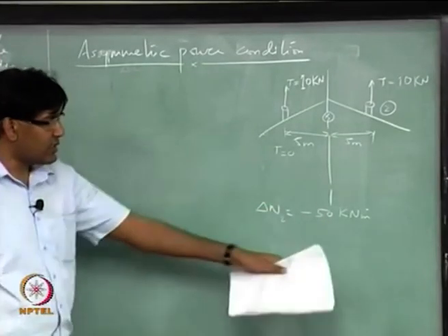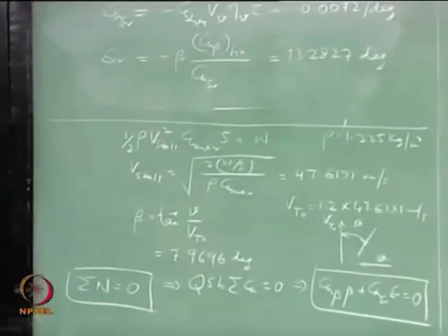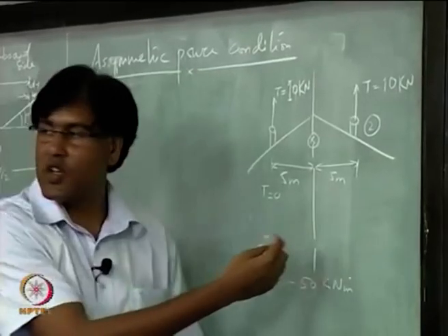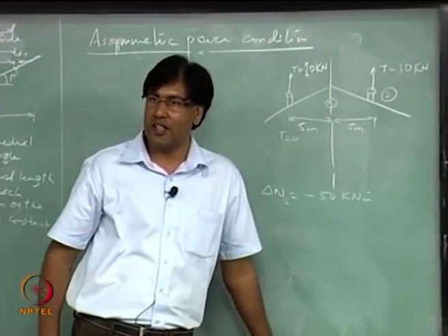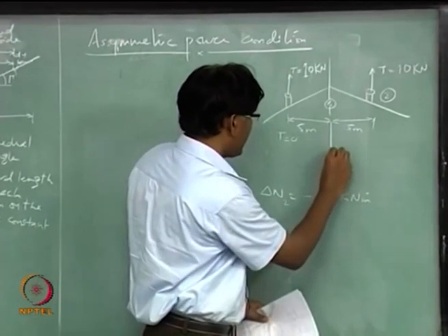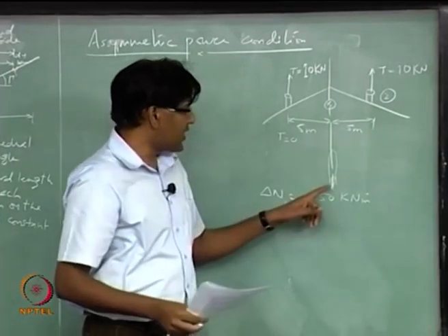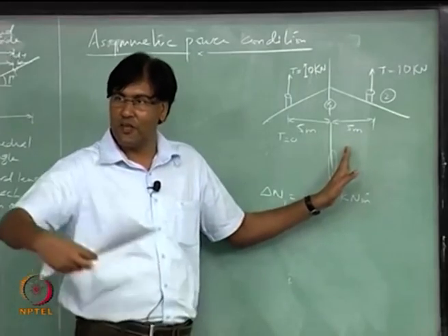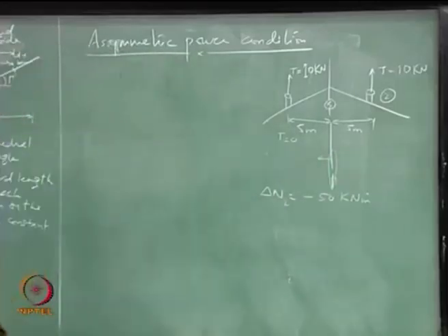So, this is the equation that you have to use. So, rudder deflection should be in which direction? Should be to your right or left. So, if I am having this vertical, so rudder deflection should be which side? This side or this side? This side, right, because you have to create a side force on this side, right.